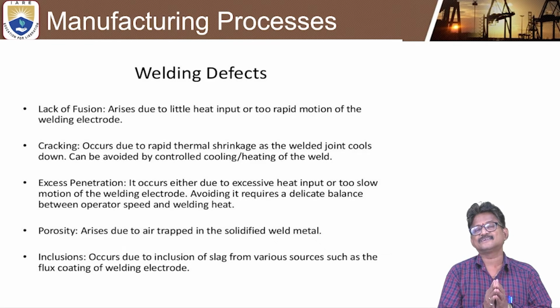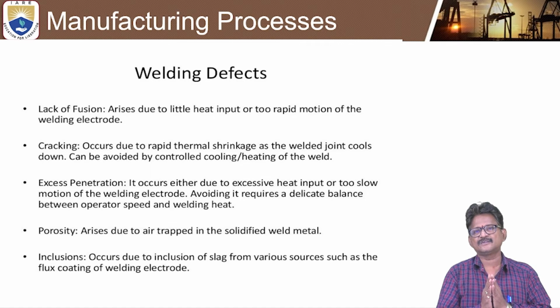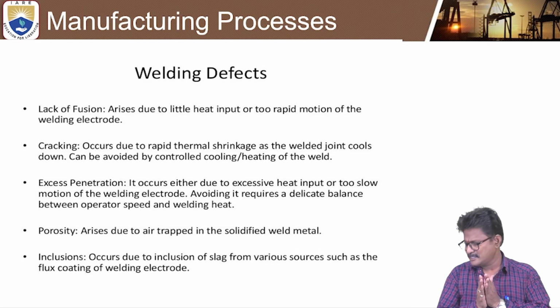If the operator speed is very slow and you apply more welding heat, more penetration occurs. So in order to have proper penetration, you definitely need to maintain the balance between the operator speed and heat input.